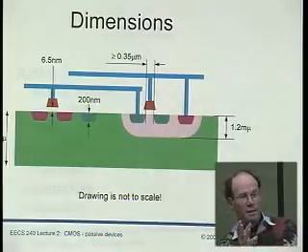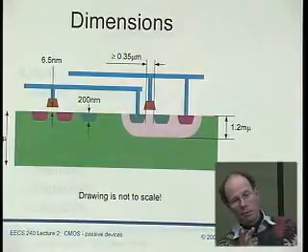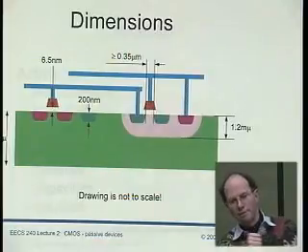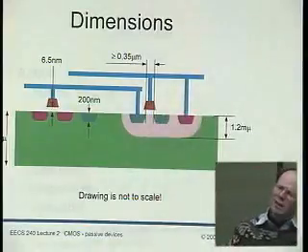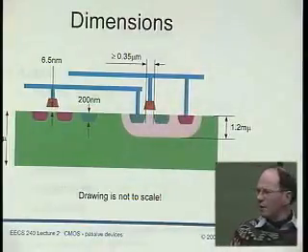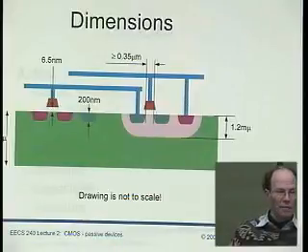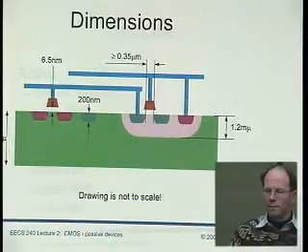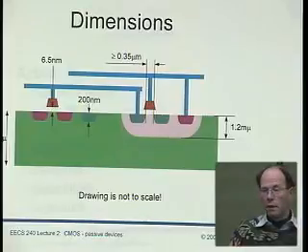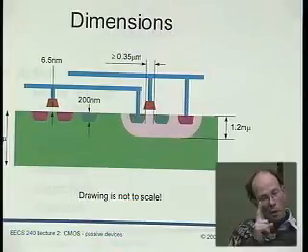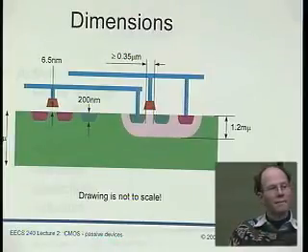Well, references. If you want to make a reference, you pretty much need a bipolar transistor, right? There is no band gap reference with, I don't know, MOSFETs. You need a bipolar. Well, we're going to use this bipolar. It's not ideal. It's not a very good bipolar, actually. But if you want to make a decent reference in CMOS, this is by a long shot the best one you can do. And of course, it avoids having to add the BiCMOS option that may not be available. And if it is, it adds a lot of money for one transistor on your entire die, right? Yes.